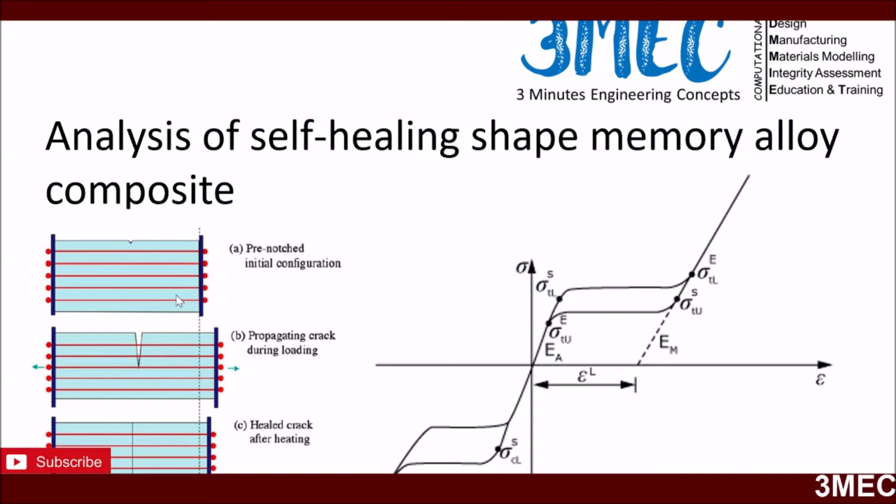In the paper, when they simulated, they used the node release technique, so they already had nodes bonded here, and then as soon as you reach the maximum stress, they start to release the nodes, and you will see this kind of crack propagation. That's what they did, because at that time ABAQUS did not have that kind of robust way of propagating cracks, or at least that was not common, I would say. So what else you can do, other than using the node release technique, is use a cohesive model here, because you know the direction of the crack, so you can use a cohesive model and define those. Or nowadays people use XFEM, which is pretty robust in ABAQUS, so you can try that as well.